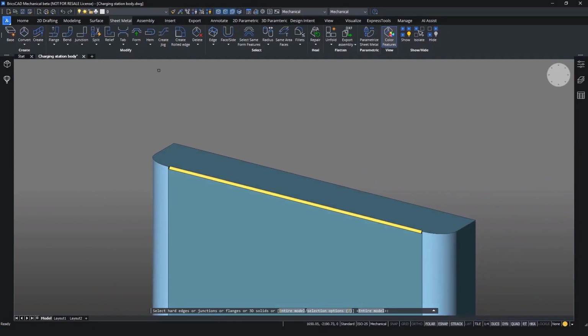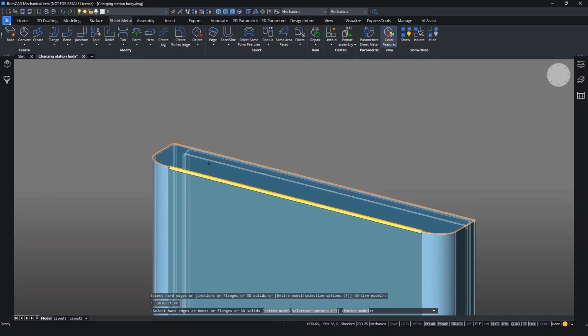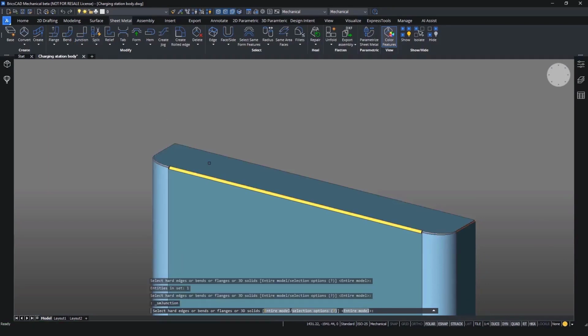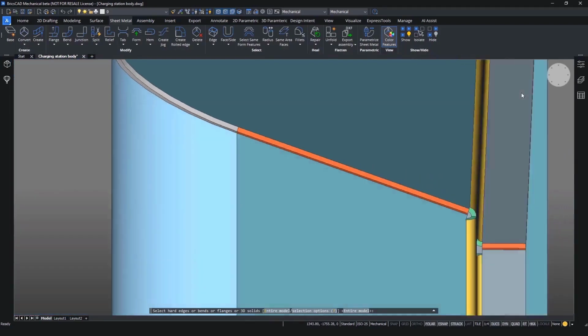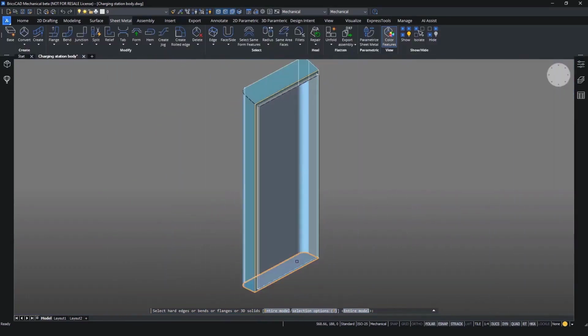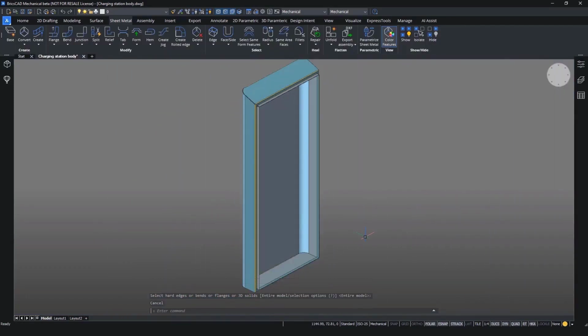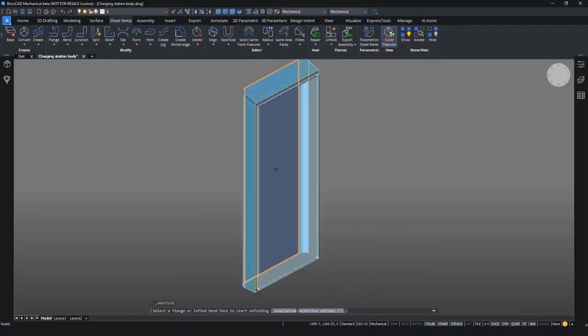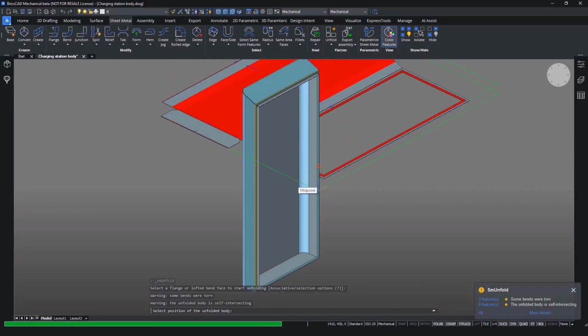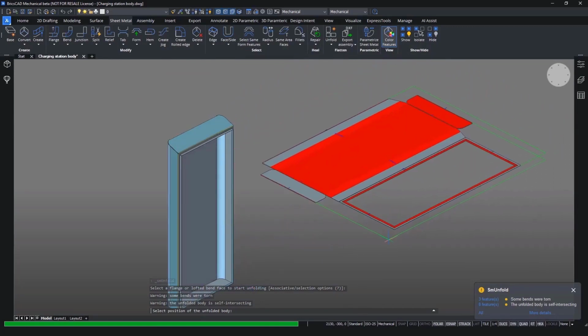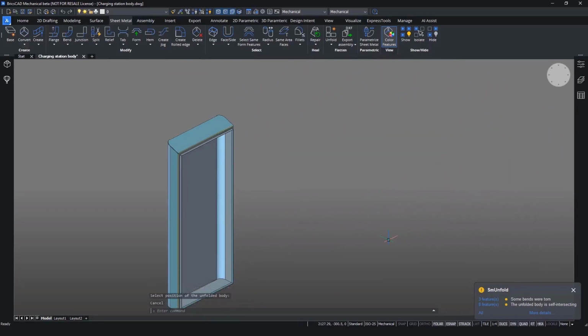We can still also define more needed junctions. As you can see, we can easily place both linear and curved junctions. One consideration to make is how this flange will split to be unfoldable. We have placed junctions, but this still needs to also have a split in the corner before it can be unfolded.